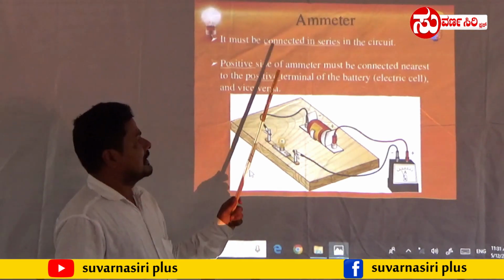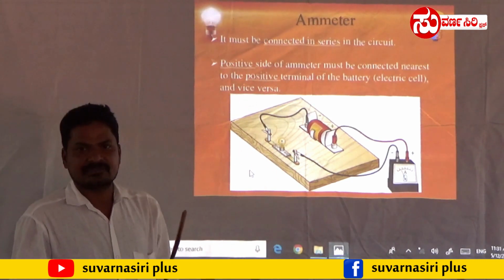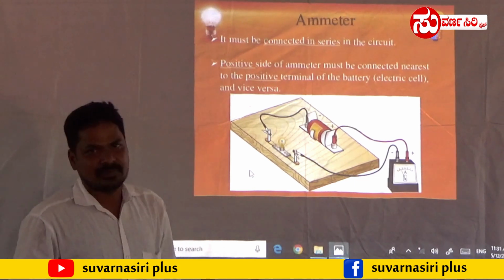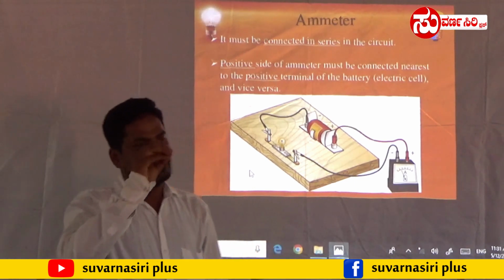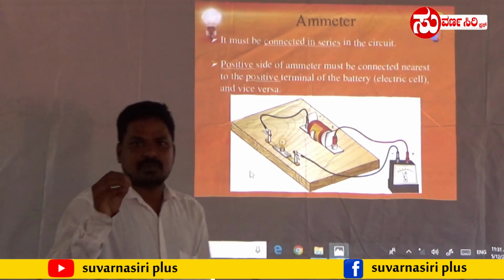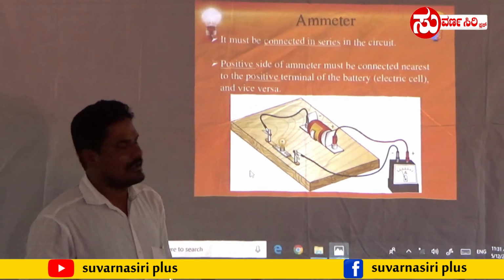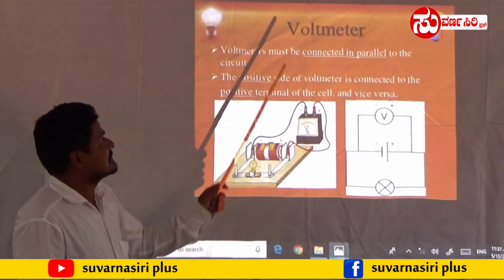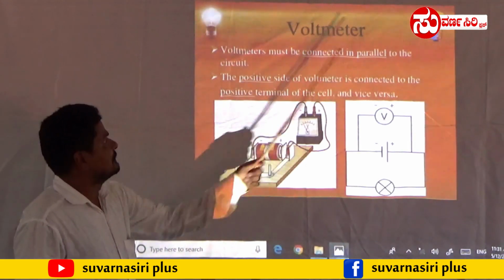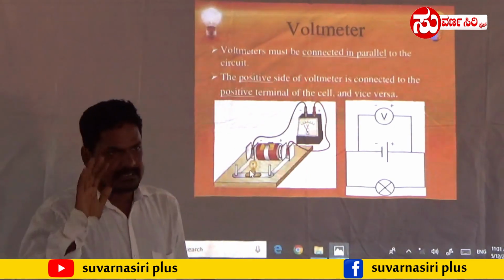We have to see what an ammeter is and how it is connected to the battery. An ammeter is a device used to measure electric current, and it is always connected in series only, with positive connected to the positive terminal and negative connected to the negative terminal of the battery. And next, there is a voltmeter. The voltmeter must be connected in parallel in the circuit.